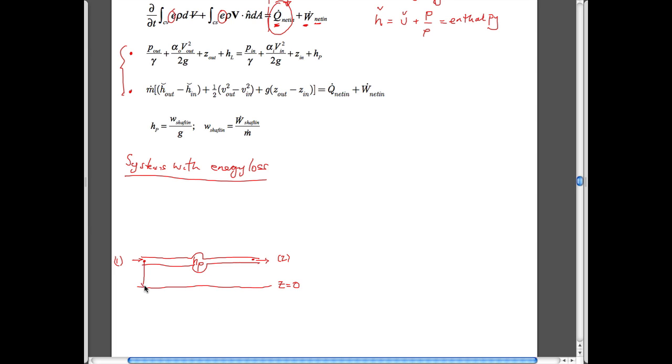And we could look at each of those components. So this component is the elevation head at this point. This happens to be the same, doesn't have to be the same, but happens to be the elevation head at this point. Let's say we might have a fluid pressure in there that we're going to deal with. The pressure term would be equal to the pressure at point 1 divided by the unit weight, and likewise, the pressure at point 2 divided by the unit weight of the flowing fluid.